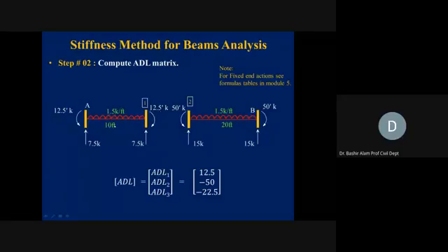So simply 1.5 times 10, which is 15. Out of this 15, half is going to the A support, half is going to this internal hinge location. So 7.5, 7.5. Similarly, these calculations you can run for the right hand side. So here W is 1.5 times L square, 20 square divided by 12. So 50 and 50 are coming.